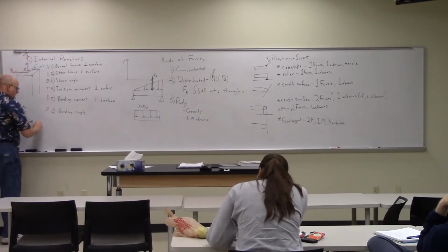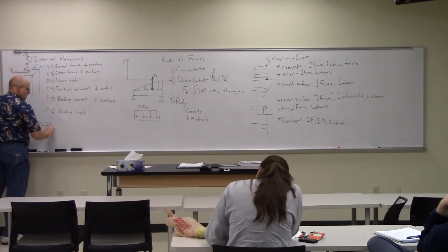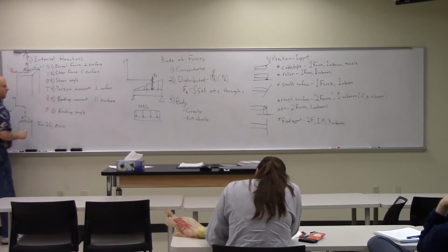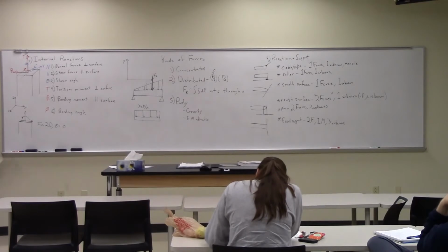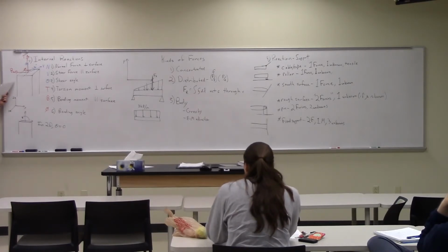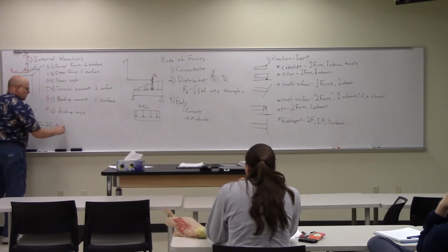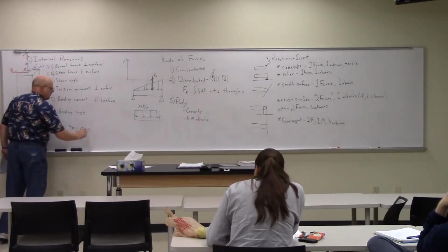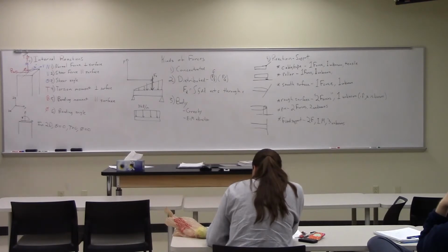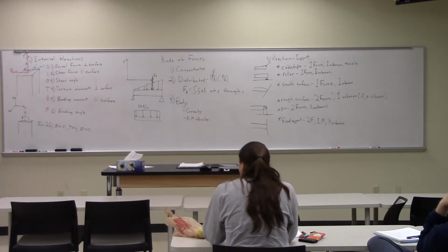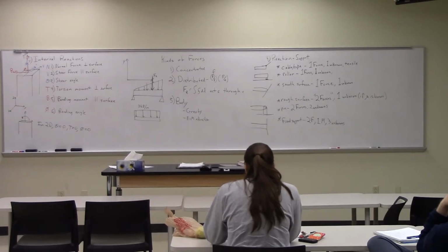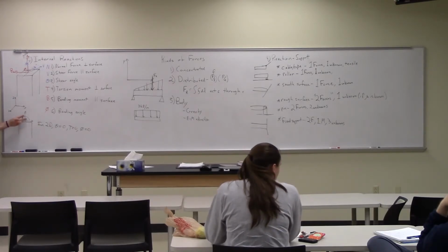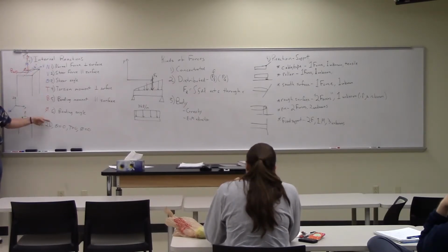So in 2D, theta equals 0, right? Because v is automatically perpendicular to n and there is no angle. And the only moment that exists is the one about z, the bending moment. There is no torsion moment, and therefore no phi. That make sense? So in 2D, we have just the 3 variables, 3 unknowns. In 3D, we have 6.